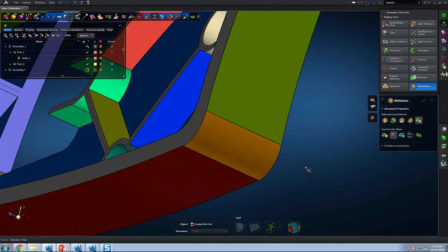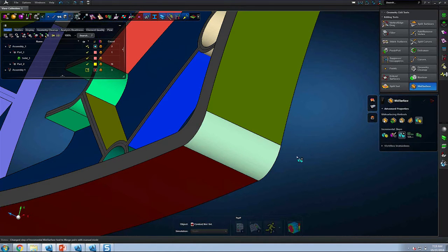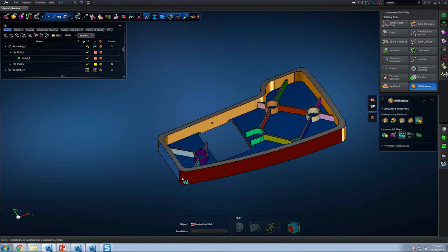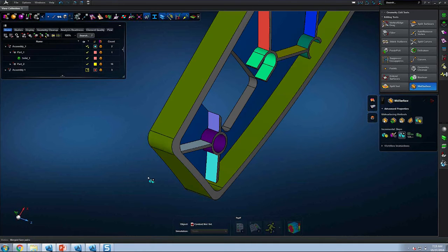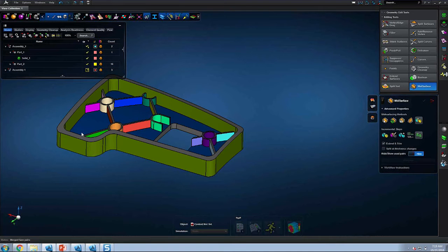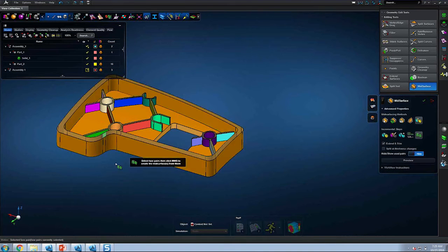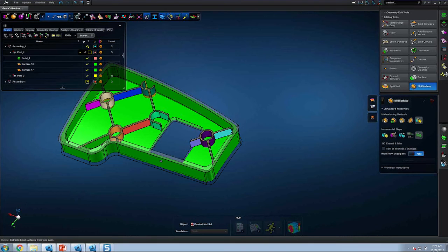Here on this other corner, I'll create a pair like before. The next button here, again, is going to allow me to create one continuous pair. Let me select all these pairs on the outer perimeter. And there we go. Now when I extract these two midsurfaces, you'll find we get one nice continuous midsurface along the outer rib. You'll find that generated in a moment, as you see here on the screen.